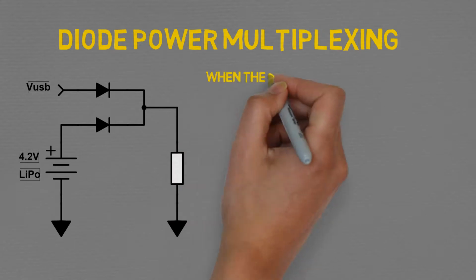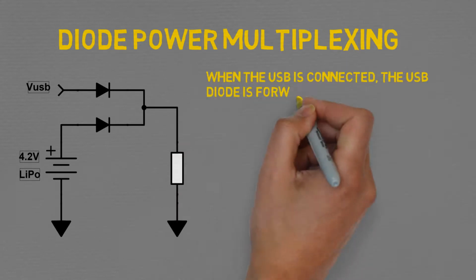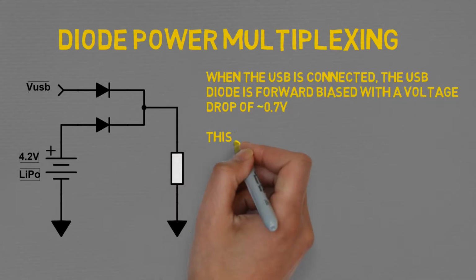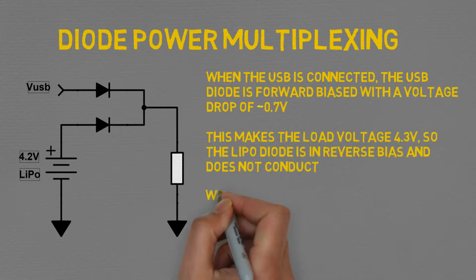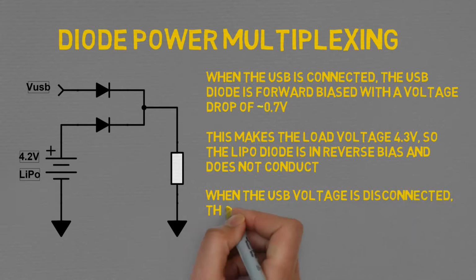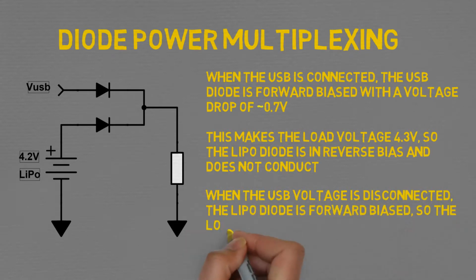When the USB supply is connected, the USB diode is forward biased with a voltage drop of roughly 0.7 volts, making the load voltage 4.3 volts, so the LiPo battery diode is in reverse bias and will not conduct. However, with the USB voltage disconnected, the LiPo diode is forward biased and the load voltage is supplied by 3.5 volts.